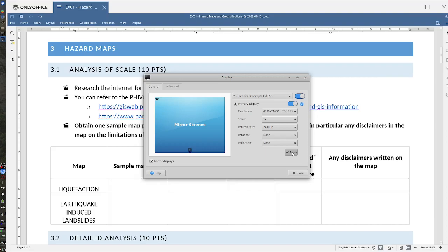Given a potential earthquake involving a fault with a surface rupture length of 10 kilometers, calculate its estimated moment magnitude. Note that this equation, the Wilson-Coppersmith, will give you a magnitude of the earthquake in units of moment magnitude. And we have here the solution.